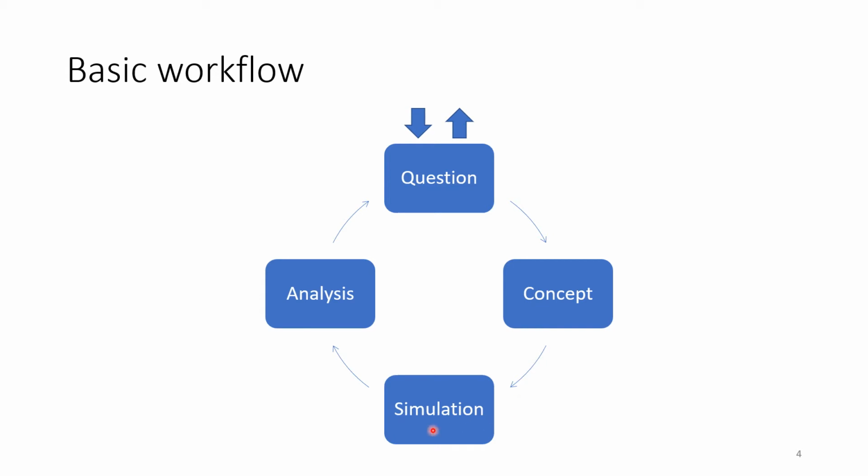And you're probably not just conducting it once, because then there is fine-tuning, spatial resolution, temporal resolution. You will notice, oh, my domain is too small. I need to run with a bigger domain because my flow velocity is higher than I expected. Whatever there is. So you do the simulation, it's a lot of work. And then there's also some kind of analysis of your results. I mean, it's not like, well, okay, I hit the run button, I got colorful pictures, and now I'm done. There's analysis, there's quality checking. Are my results feasible? Are they correct? Right? We talked about validation and verification.